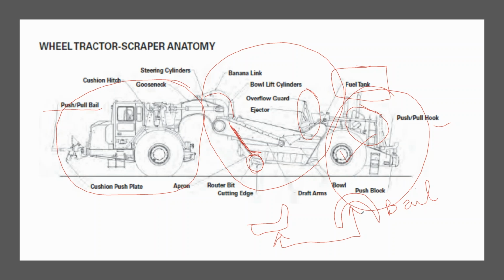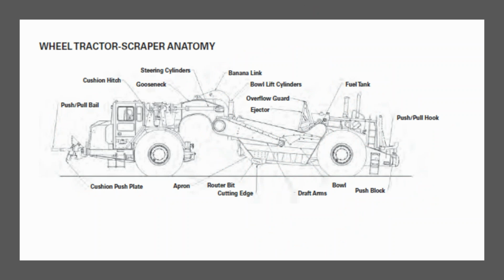Scrapers are able to do 3 different jobs, and to do them fairly well. The first is that it will cut. When we lower the bowl into the soil, it will cut and send soil up into our bowl, allowing us to fill soil in here. And that soil is collected by engaging the cutting surface of the bowl.